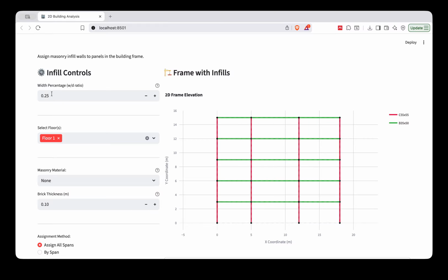So this is what the program is asking for. Here you have some estimations. For example, Priestley recommends 0.25 of the diagonal, which is the default here, but Bora recommends a third of the diagonal. So basically you have the option to select here whatever suits you the most.